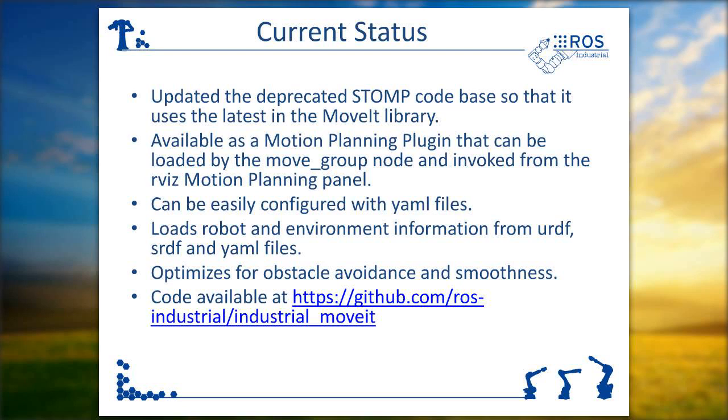One advantage is that it can be configured to meet special conditions by the use of a YAML file, and there's no need to provide extra files or support information for STOMP, since it loads the robot environment information from existing files such as the URDF, which contains your robot and environment definition, and the SRDF file, which is generated from the MoveIt setup assistant.